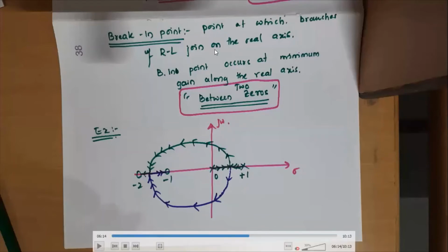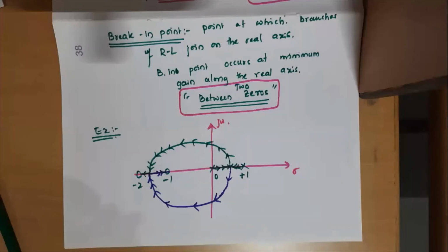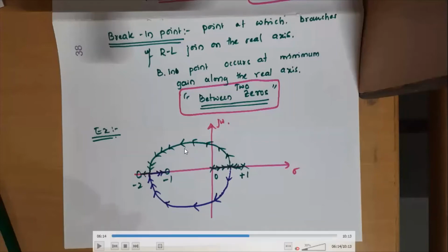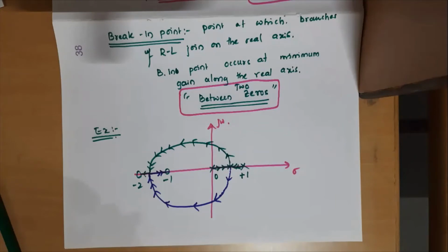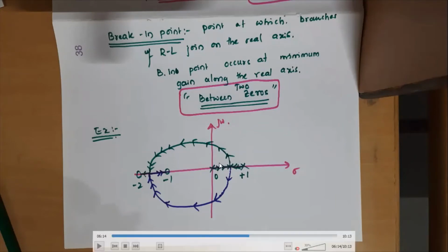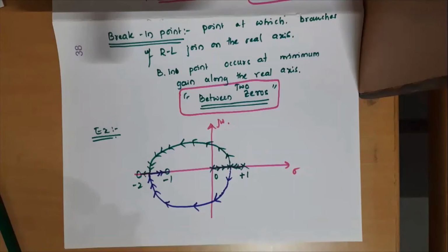Who is that asking the doubt? Lohit. Yes, sir. The closed loop poles are dependent on k. They change their position with respect to k. If there were no k, your answer is correct. When there is no k, there is no locus existing here, so it is inherently unstable. So you can adjust k to make the system stable.